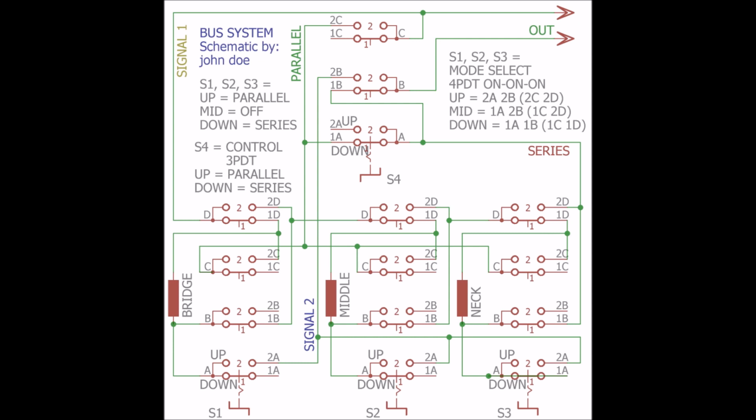In series mode, the pickups are turned off by bypassing the leads. The control switch determines which connection bus takes precedence to the output, and it also determines whether the series bus will connect to the output for SSP combinations, or to the parallel bus for PPS combinations. The SSP and or PPS buses will have to be recreated if the control switch is dispensed with.